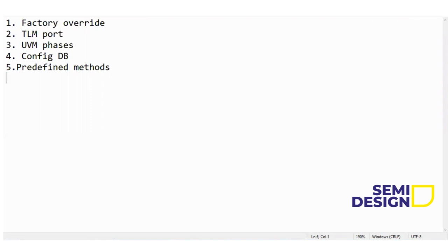And UVM has the advantage of the virtual concept. It uses virtual concept, or you can say simple polymorphism plus inheritance. These two concepts are used in UVM. That means there will be one base class. In the base class, they have defined some methods, some procedures. According to your requirement, you extend your class from the base class and use user-defined classes.